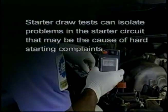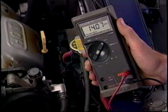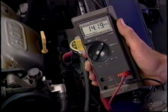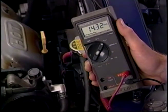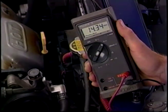Starter draw tests can isolate problems in the starter circuit that may be the cause of hard starting complaints. Generator output tests can show problems with the operating output of the alternator and should include tests to see if output is reduced as additional loads such as lights, defoggers, and air conditioning are turned on.